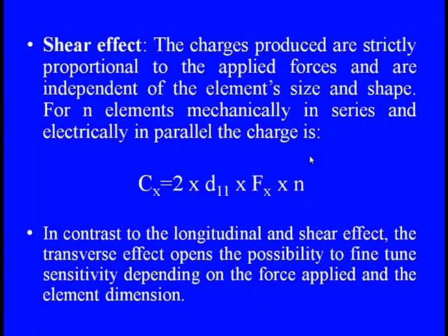And if you go to the shear effect, here also the charges produced are directly proportional to the applied force, because the shearing action is across the fibers and is independent of the element size and shape, just like the longitudinal part. And here also the number of elements are in series mechanically and parallel electrically with the charges. So the amount of charge produced is equal to 2 times d11 Fx into n.